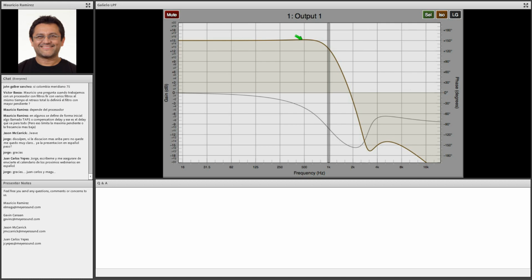But also, if we pay attention to the area before the cutoff frequency, this area shows a little bit of increase. And this little bit of increase goes up and down of around half of a dB. So this means that this area is rippling the pass band. For this reason, as we can see here, this is an elliptic filter.